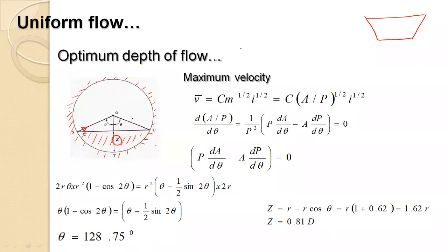Earlier, if you can remember, I fixed the cross-sectional area, flow area, and then looked at how area would change with the water depth and then the side slopes. But here, I can't fix the flow area. The reason is this water depth will make the flow area dependent on the water depth only. Now there is no side slope to change the area. Area is only dependent on the water depth.